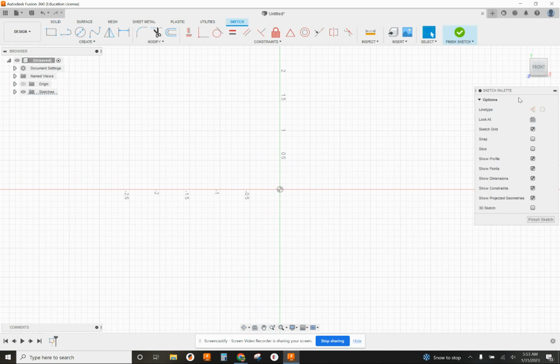And the first thing we're going to do is use the line type construction. We're going to create a horizontal line right from the datum. Click there and then go 180 degrees over, so go to the left and hit escape. So now we have this line. We're going to need this line in order to do our revolve feature later on.